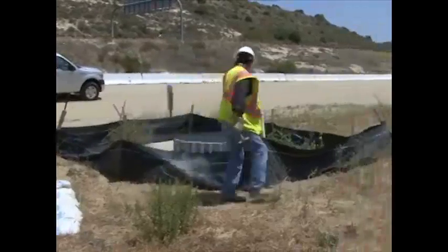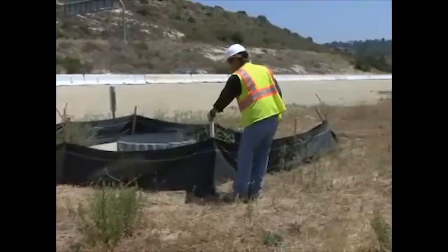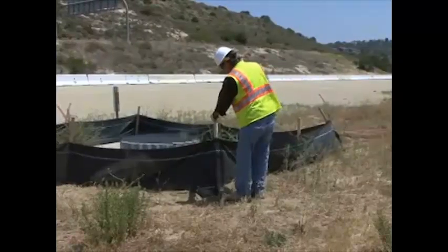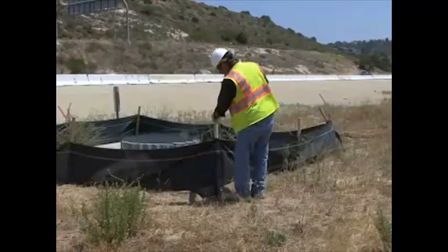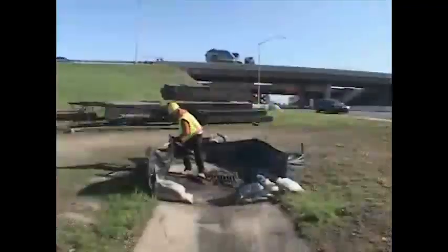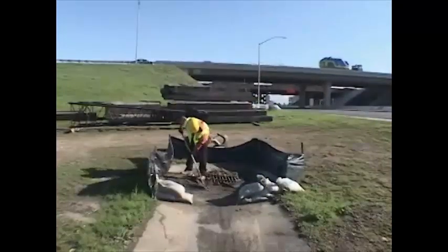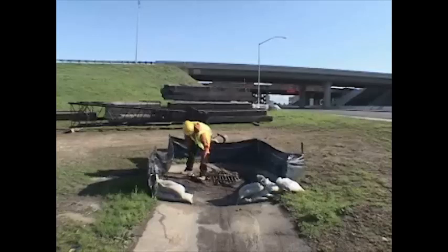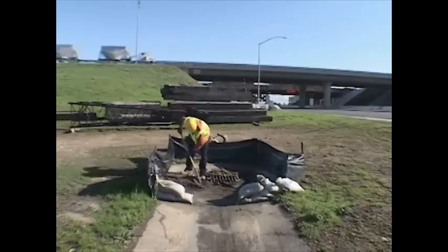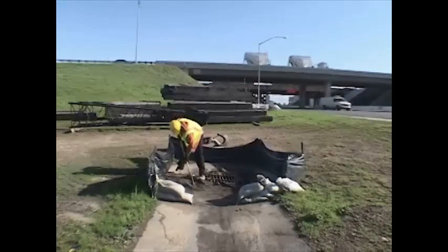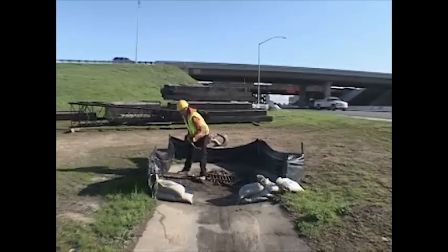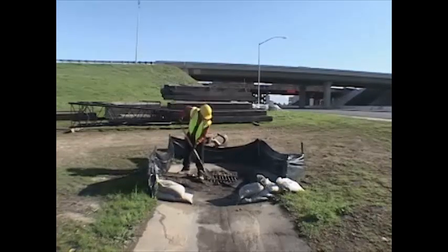Maintain the temporary silt fence to provide a sediment holding capacity of approximately 1/3 the height of the silt fence fabric above ground. Remove sediment in excess of 2 inches above the surface of the erosion control blanket or geotextile fabric. Remove sediment from the sediment trap when the volume has been reduced by approximately 1/2.